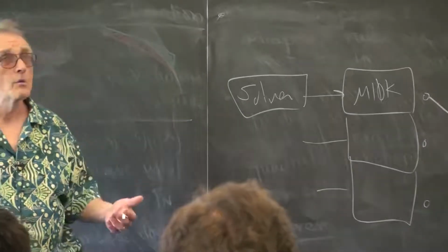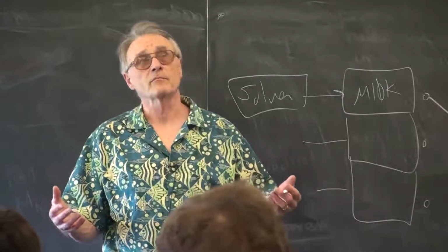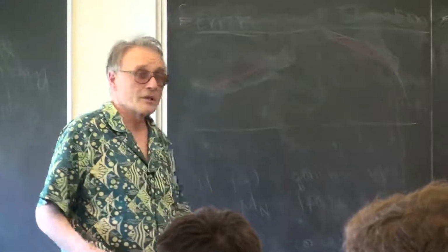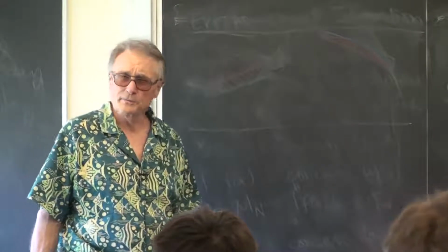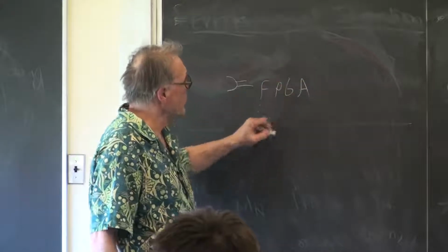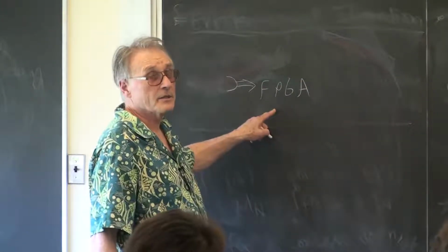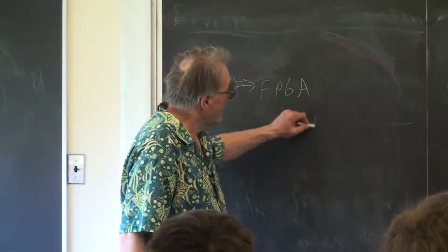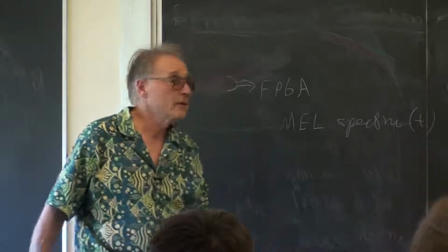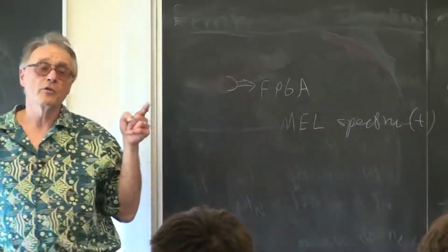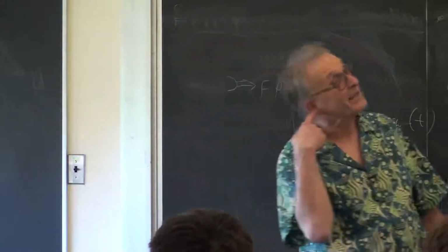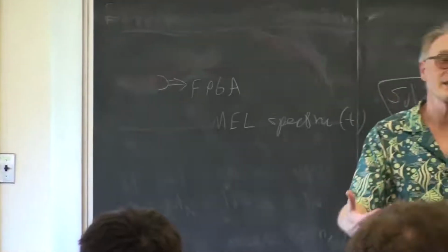or let's say uses the FPGA to pre-process some information for the HPS. What comes to mind in this is word recognition, where you have a microphone hooked to the FPGA side, which is going to extract the MEL spectrum versus time, and then pass off the MEL spectrum versus time to the HPS, so that the front end, which is the FPGA, acts like the cochlea of your ear, which does the frequency analysis and sends the frequency analysis to your brain.